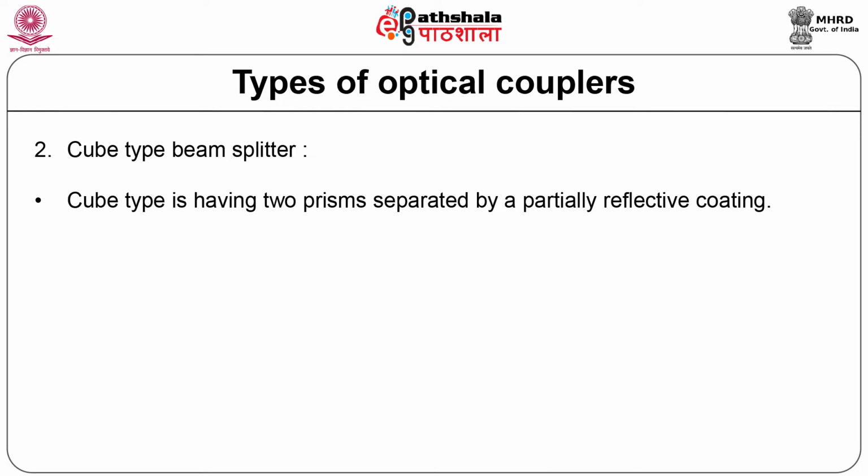reflective coating. It is important to note that a beam splitter cannot be employed by itself for dividing power among fibers. The presence of the splitter in the path of light is equivalent to a gap, which provides large losses to the diverging rays emitted by the input fiber.